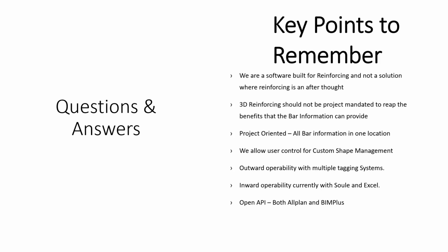One of them is, can we do a standee shape? Yes, within our Rebar Shape Manager, we can create 3D shapes. Frank showed you very quickly, we can do in-outs, which will produce the 3D shape. As soon as you define it within the Shape Manager, you give it a name, and ALLPLAN will then recognize it. If it has the exact same shape as what's in your shape library, it will create that. So we do have the ability to create these standees.